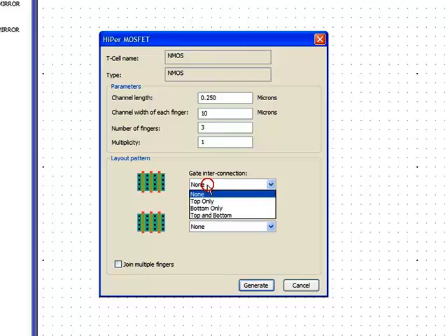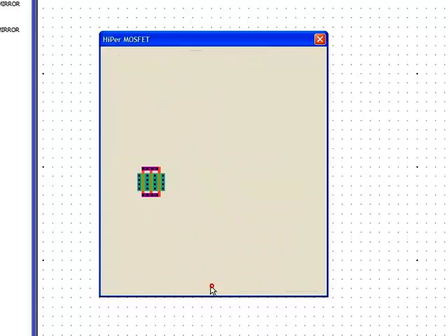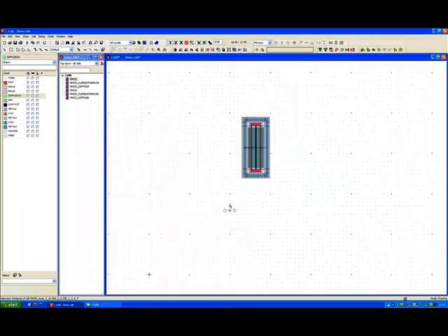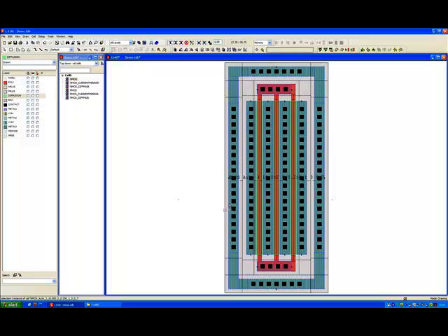And it's quite feature rich in terms of where you want your gate connections. Let's go top and bottom, and let's add a guard ring all the way around. So effectively what we have here is a very simple MOS device. All the layout person has had to do, in 15 minutes for this technology, is map the technology layers across and also enter the design rules. And the minute that is done, they now have silicon aware parameterized cells.